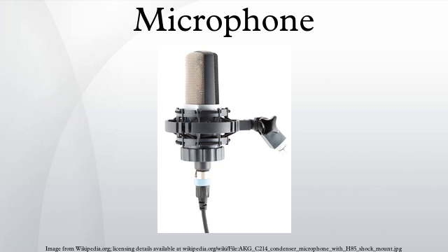Unidirectional. A unidirectional microphone is sensitive to sounds from only one direction. The diagram above illustrates a number of these patterns. The microphone faces upwards in each diagram. The sound intensity for a particular frequency is plotted for angles radially from 0 to 360 degrees. Cardioid. The most common unidirectional microphone is a cardioid microphone, so named because the sensitivity pattern is a cardioid.